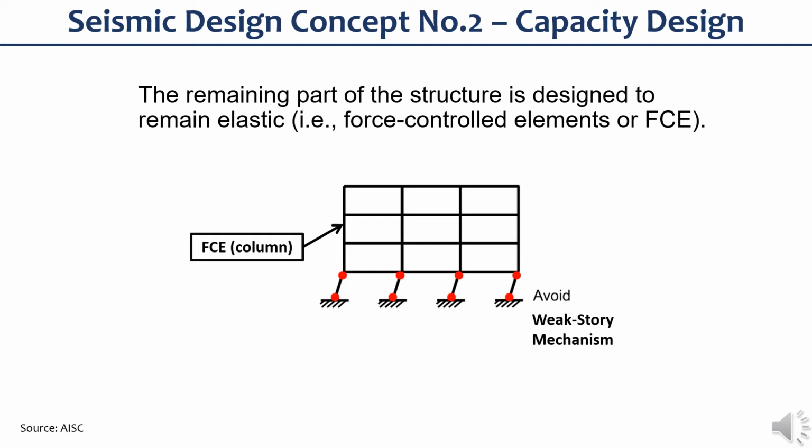When these elements yield, they limit the force that can be transmitted to other elements, effectively shielding them from overstress and allowing them to resist design earthquake excitation while they remain elastic. This practice permits the elements that are not expected to yield or experience inelastic behavior to be designed and specified without difficult detailing practices intended to provide for ductile behavior.